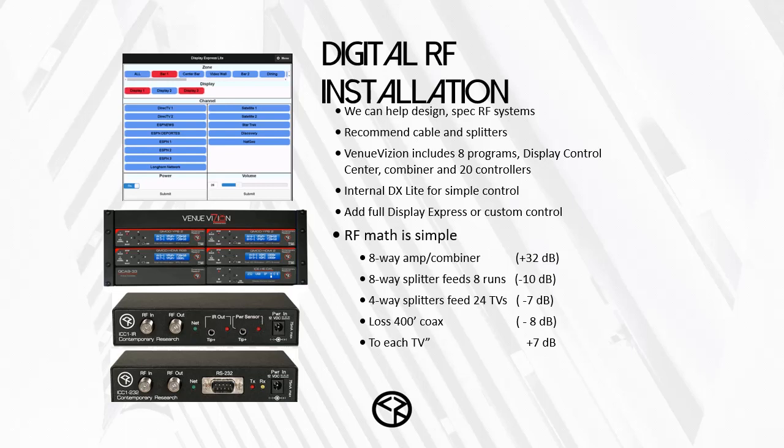You can easily use 0 as the perfect number and go plus 10 or minus 10, but we always like to have a little more power than 0, so if something isn't wired there or something isn't wired there, we lose a little bit. It doesn't really matter. The TV itself works fine with minus 10 to plus 10, and we find many sets like LG, I can hit those TVs a lot harder. Most TVs don't like RF levels above 15, so that's why we try to stay under 10 in our basic design.